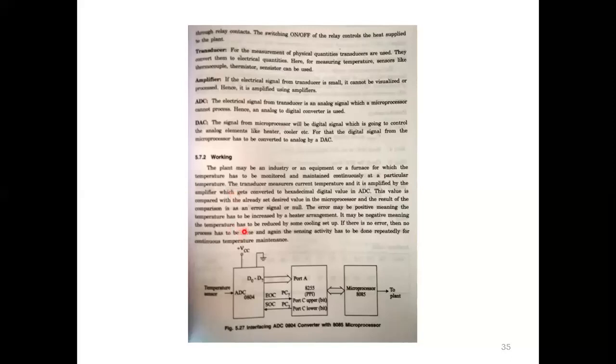Okay, in 8085 we don't have input output ports, so we add the 8255 peripheral interface. Already we discussed in the last class that 8255 is a port generating programmable peripheral interface. It has input output ports, port A, port B, and port C. Here we are using the 8255 for generating the ports instead of the 8085.